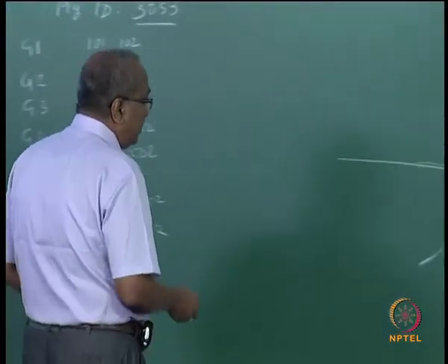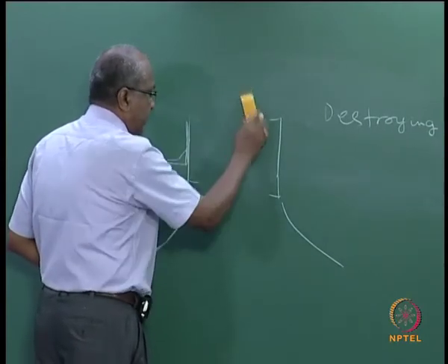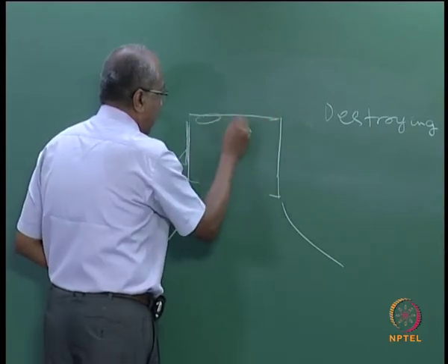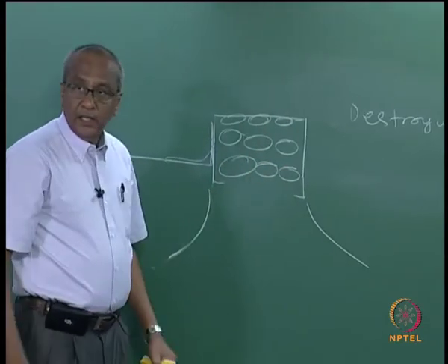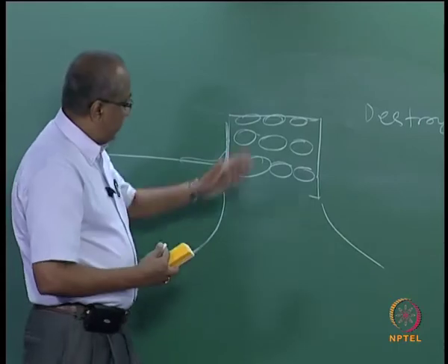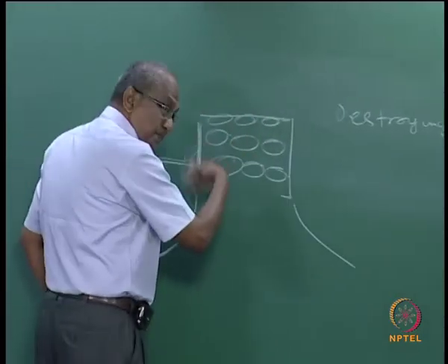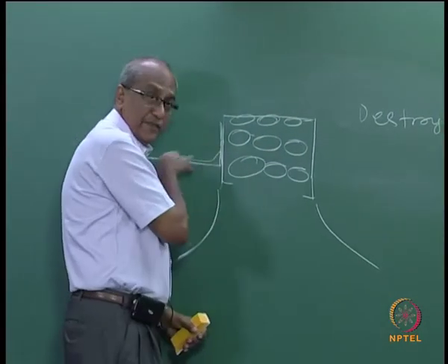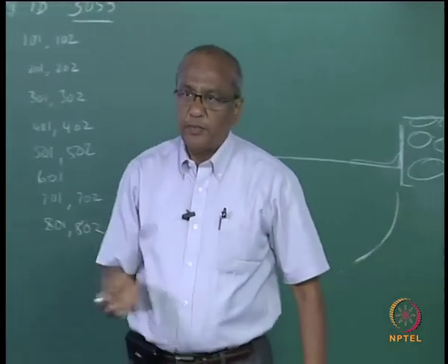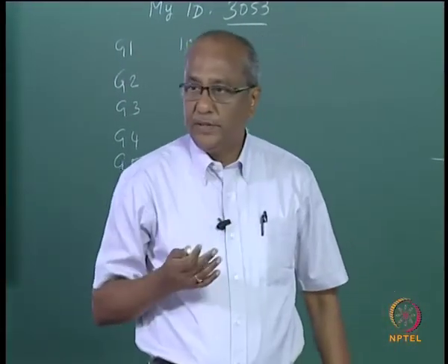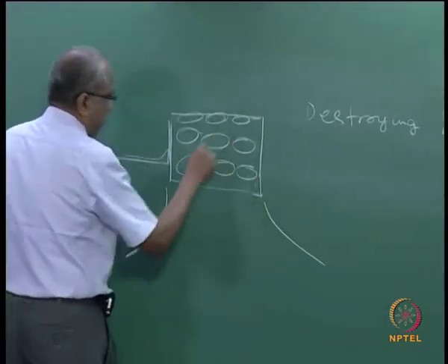So the other possibility, the efforts were to create some kind of a porous medium. You still have a structure like this, but then you have the same principle, plus in addition the dissipation can be because of the waves running through the porous medium. You understand? We have already seen that that is the principle on which your rubble mound breakwater is designed, right? Is that clear?